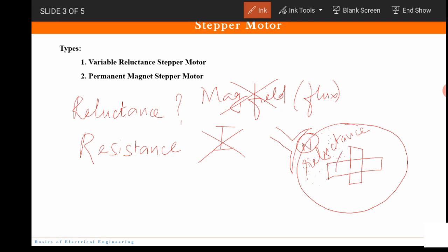So when this moves, it means now this is made up of ferromagnetic material. And what is the property of ferromagnetic material? They are attracted by the magnets. It means they support magnetic flux. And the very big advantage of ferromagnetic material is magnetic lines of force go inside the ferromagnetic material or pass through it. So earlier there was an air gap, but when this moves, because of this movement the reluctance is changing.